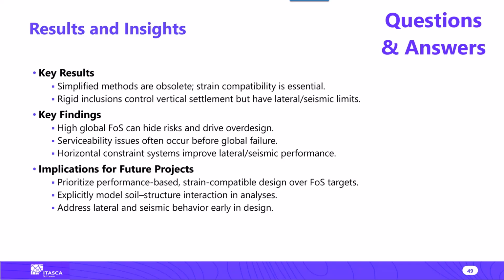So, yes, in a few cases I've investigated, and I'm a proponent of that technology personally. In a few cases, I was able to break through. There is a sort of skepticism, I don't know for what reason. Instead of using this LTP with geogrid, use a sort of LTP made with lean concrete and maybe a mild reinforcement inside, that would greatly solve all these issues and also simplify the construction, in my view. So the short answer is yes. In a few cases I've been able, and I like that idea in general.